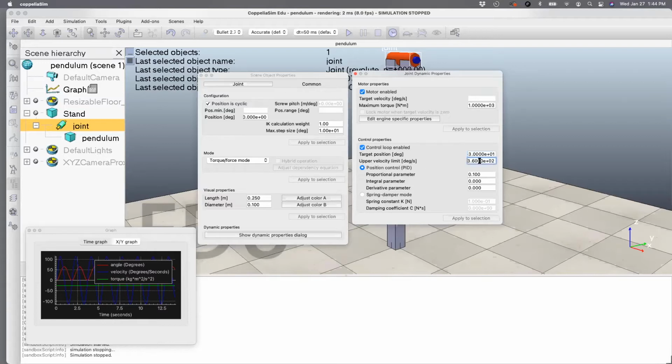We want a velocity limit. This is the same thing as the torque limit earlier. So you want to specify a big enough limit so that it never really hits that. So let's say 1000. Okay. Well, that's actually small because it's degrees per second. Let's just make it 9000. So it never hits that. And now we need to set the PID control gain. So let's say 100, integral 1. I always like to put a small integral gain, and then velocity is 10.